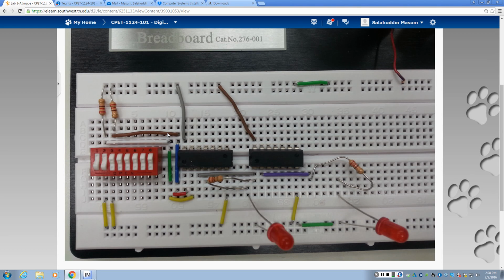You can pick any column here, no matter which column you pick, each column is shorted. In each column, in this breadboard, you have 5 points. All those 5 points are actually the same point. That means it doesn't matter which point you pick when you connect the wire. For example, let's say you have a chocolate wire.